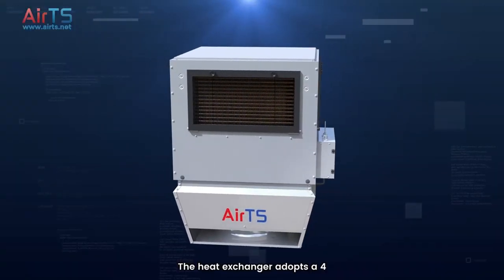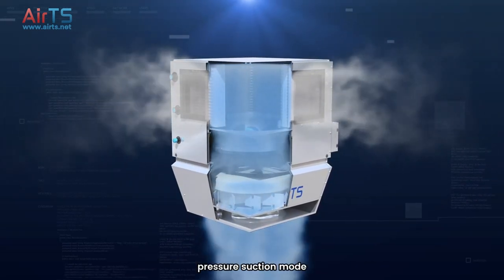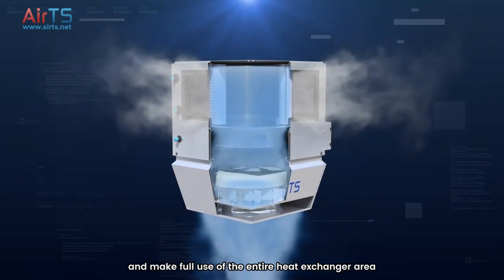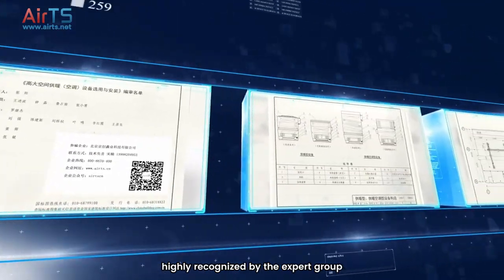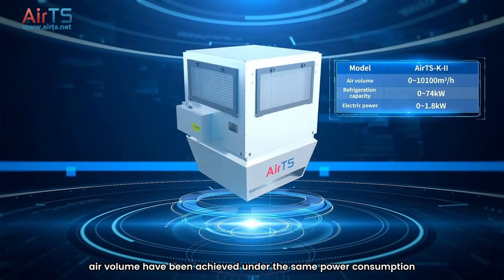The heat exchanger adopts a four-sided return air design and has a smaller wind resistance. At the same time, the fan is placed at the bottom and works in a negative pressure suction mode, which can achieve a uniform airflow velocity distribution at all positions of the heat exchanger and make full use of the entire heat exchanger area. The overall structural design of the device has been highly recognized by the expert group, and a large cooling capacity and air volume have been achieved under the same power consumption.